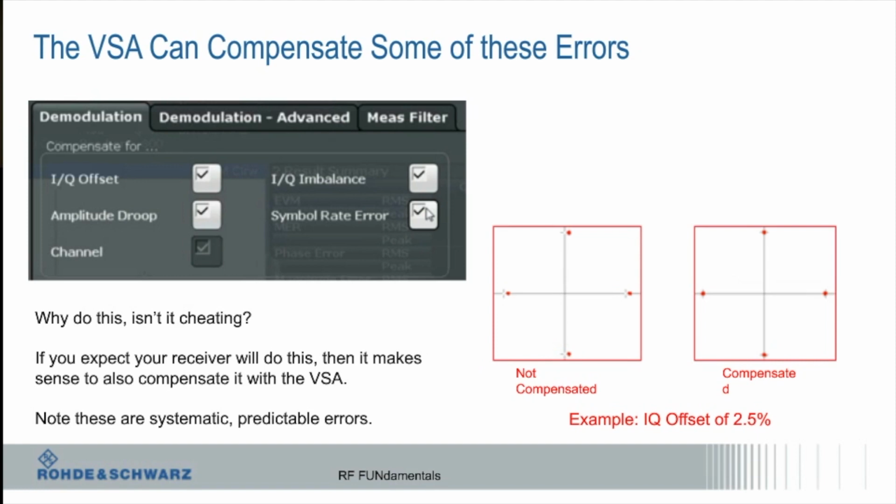And I can measure phase noise much more accurately with much more dynamic range with a spectrum analyzer, or actually a phase noise analyzer, than you can with a scope, because I can vary the bandwidth that I'm looking at. So if you remember when I was talking about the noise bandwidth, changing the noise bandwidth as a function of resolution bandwidth filters, things like that, I can't do that on a scope. A scope pretty much looks at a broadband thing, and it's going to take that distribution. So I can't change the noise levels that the analyzer sees. Plus, on a spectrum analyzer or a signal analyzer, I typically have more bits of resolution in my measurement.